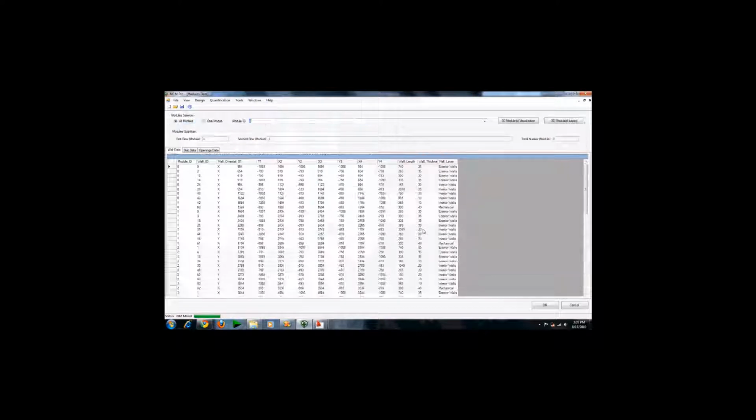This warning message is related to the dimension of the modules that I created. We can see that we have a violation in the width because the maximum width was this value, which is bigger than the default value. This default value are related to normal cases, but usually when we use construction project, some special permit can be obtained from the city of Edmonton or another city. So we can choose either abort to stop the operation, retry to choose another walls, or ignore to keep going with the process. So I'm gonna say ignore.